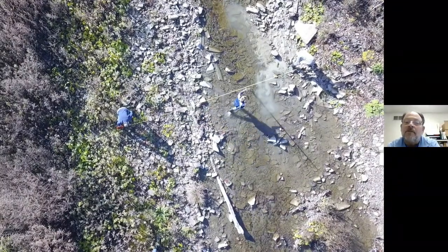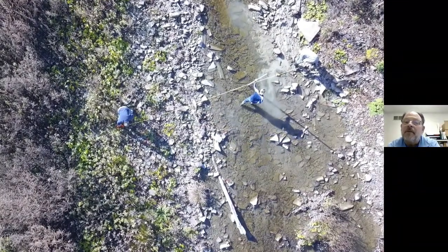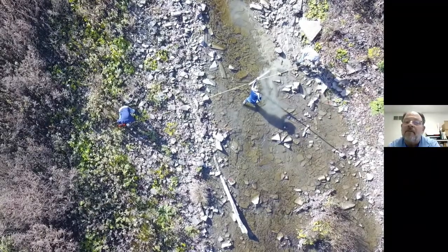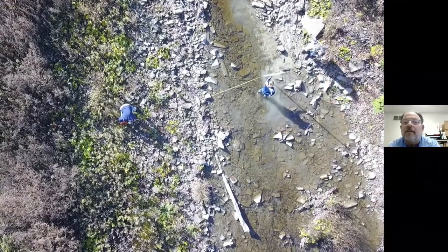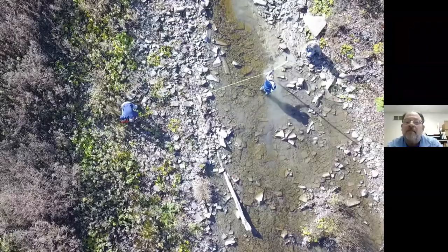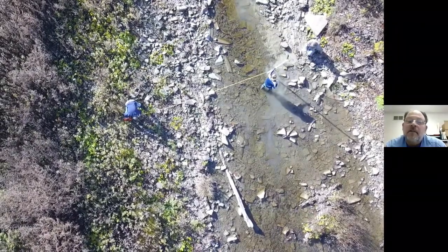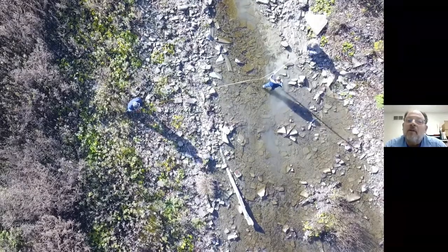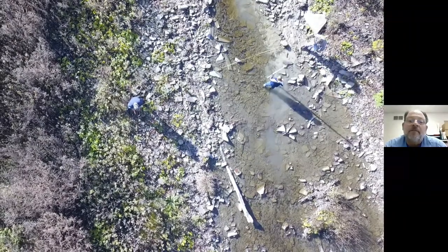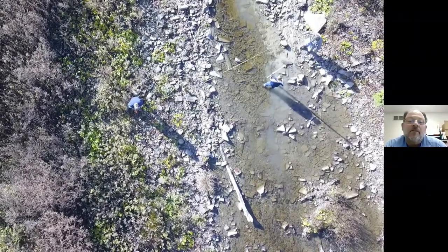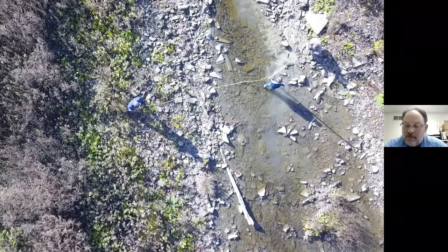There she goes. She's going out to measure the deepest part of that channel to give us a depth. And that gives us the depth. We can sometimes take these measurements and see how they match to the regional curves and see if we're somewhat close, or if they're way off, then we have to take another look, or look at another cross section.